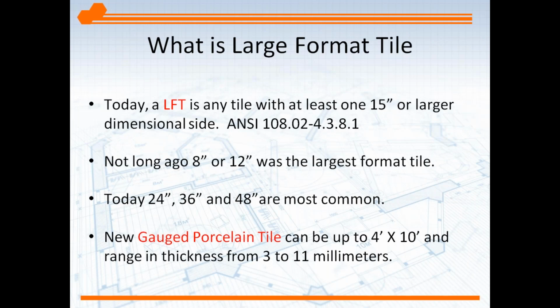Okay, what is large format tile? Large format tile is any tile with at least one dimensional side 15 inches or larger. So as per ANSI, that's the classification of large format tile: 15 inches or larger on one side. That would mean a 15 by 3, a 16 by 3, or a 16 by 6 would all meet that classification of large format tile. And there are things that change as far as installation and surface prep when we get to that classification. Obviously we're going to talk about that.